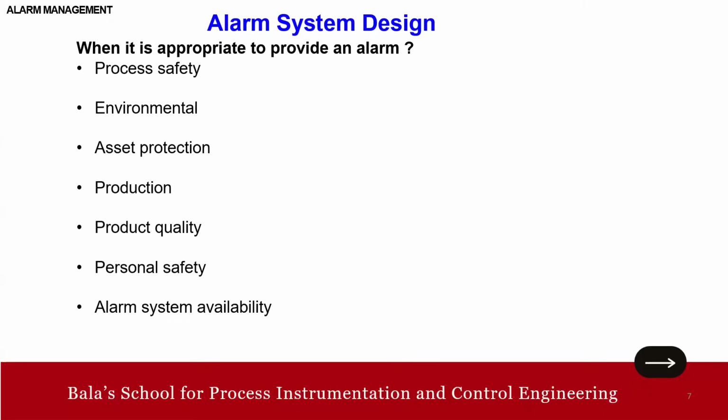What are all the practical considerations for alarm design? Okay, in that I'm going to talk many more actually. Types of alarm. Okay, it's very important. The types of alarm means absolute alarm, bit pattern alarm, calculated alarm, system alarm, deviation alarm. Very important aspects. And first up alarm, you would have heard, right? First up alarm, and how to select alarm settings. So those things also I'll focus.